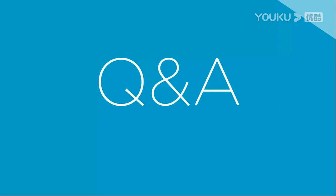Could Bluetooth 5.2 LE Audio be added to current nRF51 and nRF52 chips by SoftDevice? This will be difficult to do and not something that we will be able to support because the audio solution will be in the nRF Connect SDK, and on nRF51 we will not have LE Audio support, but we will have it on the nRF52 series, or the larger memory devices in the nRF52 series, nRF52832 and above.